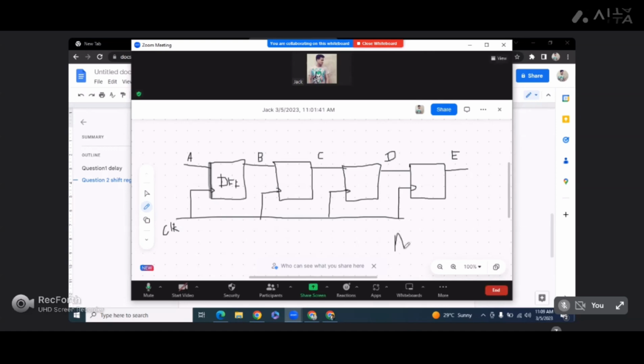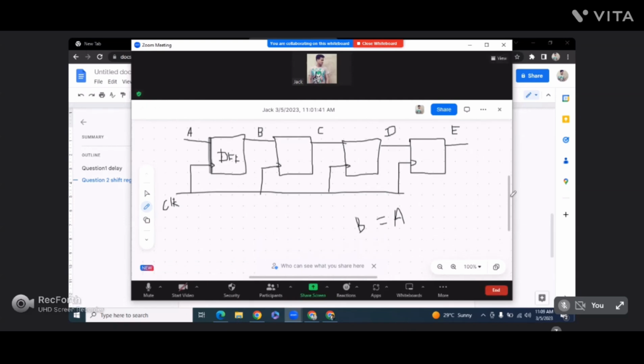Bindu, I just want to know, if we first write A is assigned to B, yeah, then B is assigned to C, then I think only one block will form, sir. We can't make a shift register with 4 blocks, like 4-bit, we can't make it, sir. Okay. So it works as a single flip flop. Yeah. Okay.